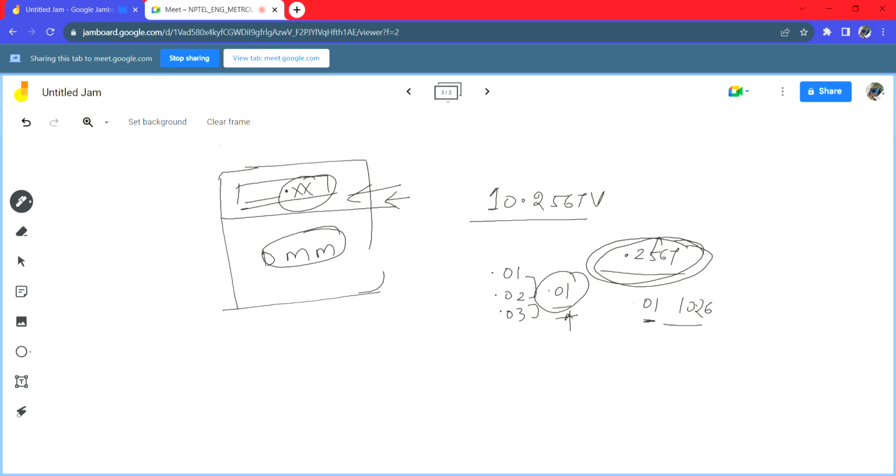This value would go for approximation, and these two digits it will approximate to the next higher digit that is available for display. So 10.2567, my device would read as 10.26. This happens when the resolution is 0.01 in these cases.